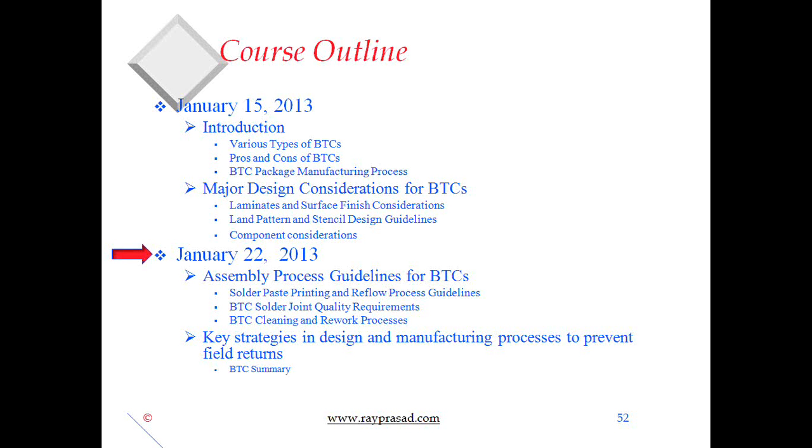By the way, this is not for everybody. We are pushing the edge of the technology. So in terms of the answer, go to the limit as to how much paste you can print. Go to the maximum just before you start causing bridging. And we are talking about a powder size of type 5 or 6 paste, if my assumption is right about the pitch of this flip chip.